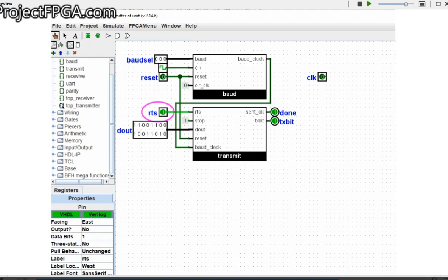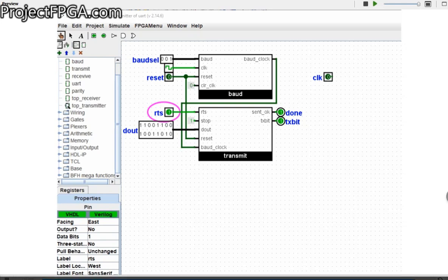If the stop bit was set to 0, the transmission would occur multiple times. Once it ends, it resumes again. But here it is set to 1, and is tied to high or 1. So what happens is, once it's done transmitting the first one, it stops until I reset it and it starts back afresh. So I will repeat it with a different baud rate.